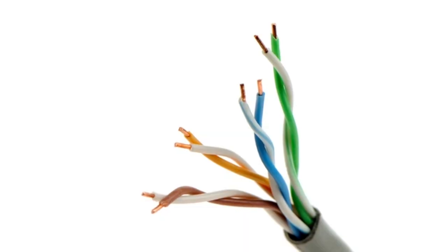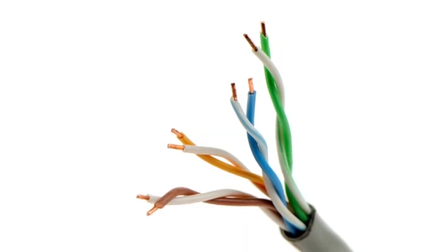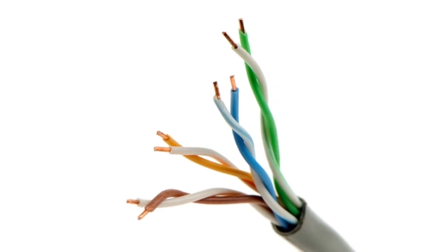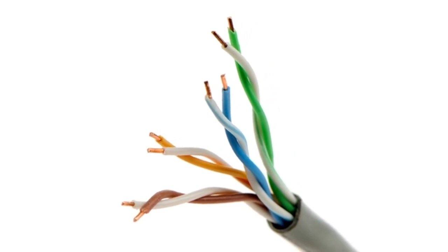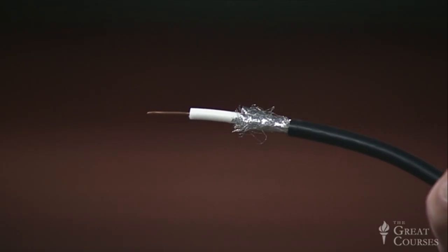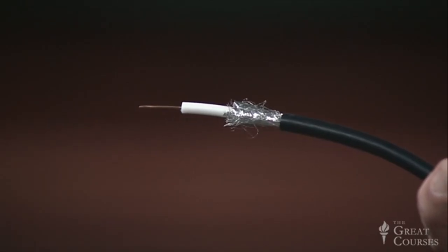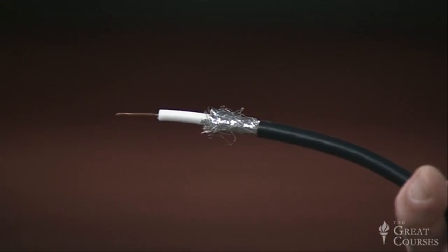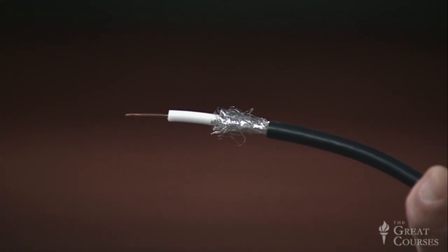Anytime electrons move at varying speed, they generate electromagnetic radiation that propagates through space at the speed of light. We've seen this phenomenon before. The reason twisted copper wires are twisted is to reduce the adverse effects of electromagnetic radiation emanating from the wires as current flows through them. Coaxial cable uses a metal shield to contain the electromagnetic field within the cable and to protect against electromagnetic interference from outside.